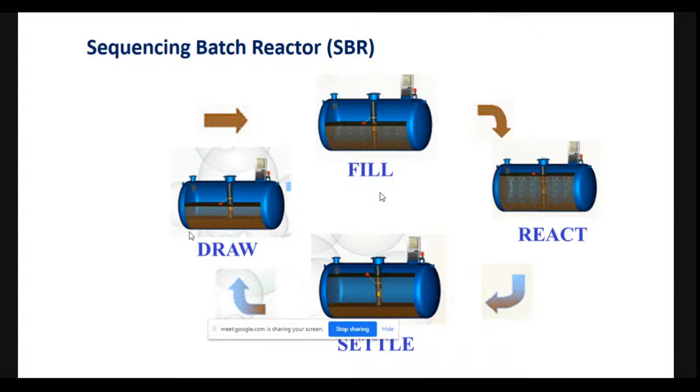So you are seeing a simplified system, which is called a sequencing batch reactor, which has been consolidated into a small tank. This is one of the systems which I worked on in France during my postdoctoral fellowship. There was a patent designed for this, and it was commercially produced by a company and supplied to the cheese manufacturing industry. France is famous for cheese manufacturing, where the wash water in the cheese making industry, which contains very fine suspended solids and milk particles, had to be treated, and that's where we tried to use these small systems, which can be automatically operated.